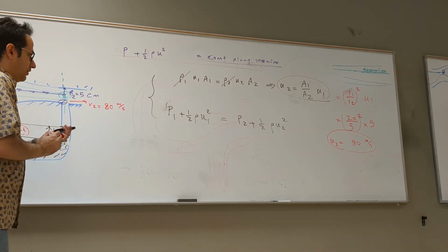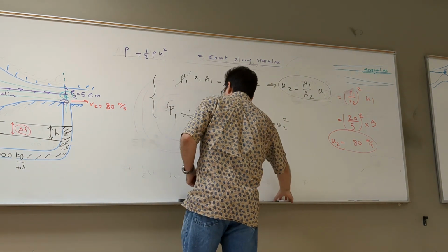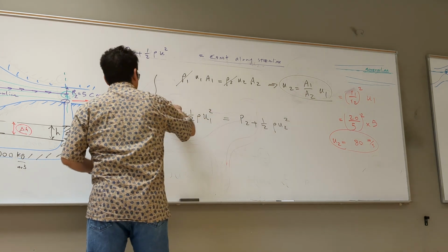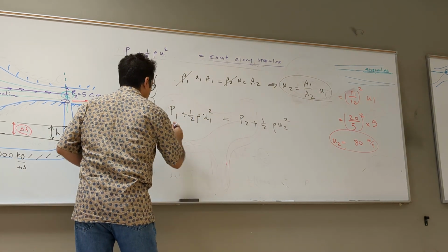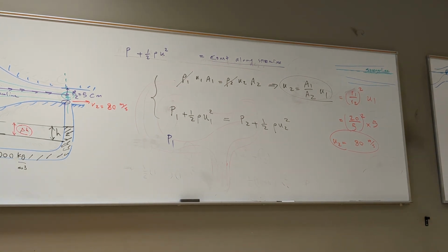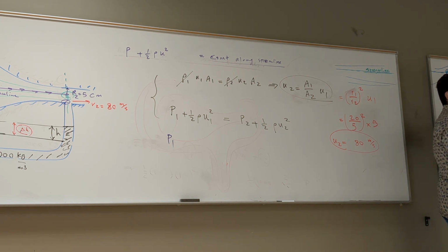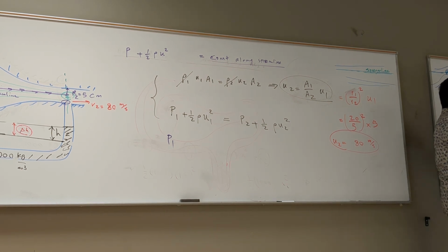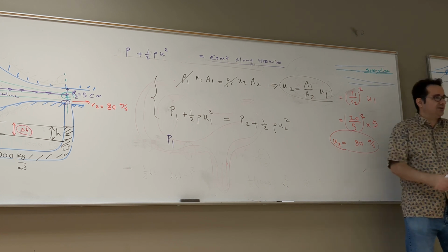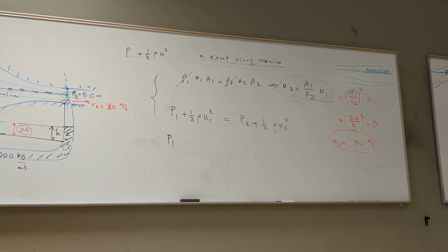Now let's work on the Bernoulli equation. To say 1/2 of P1. Do I have P1? Do I have pressure here? Back to the question that Edwinas asked. He asked how come we have a pressure here at this aircraft, and I said put a pressure sensor here, and it was a magic sensor that measured pressure. But it's not really magic. You can use a U-tube and measure it, and that's what I'm trying to get to right now.